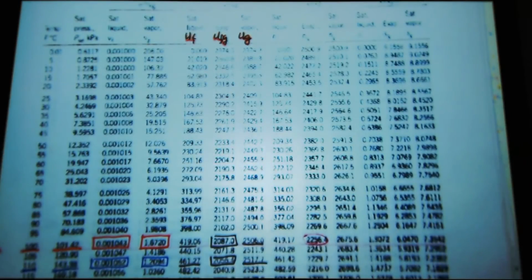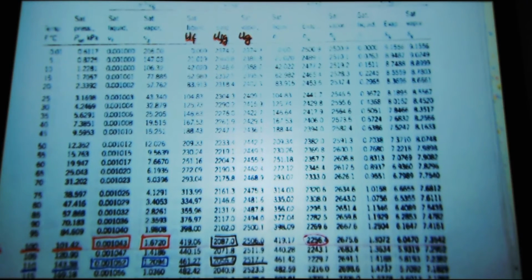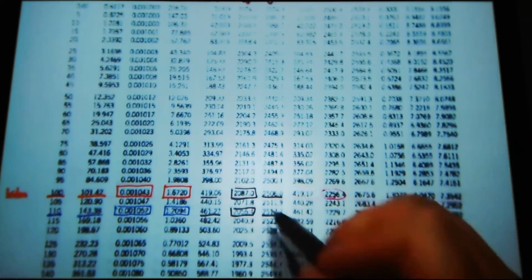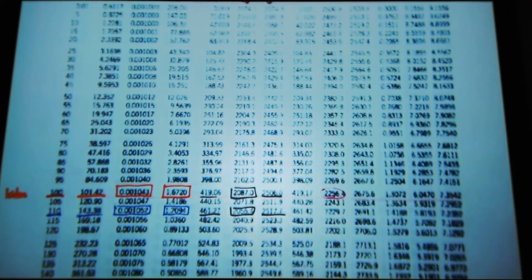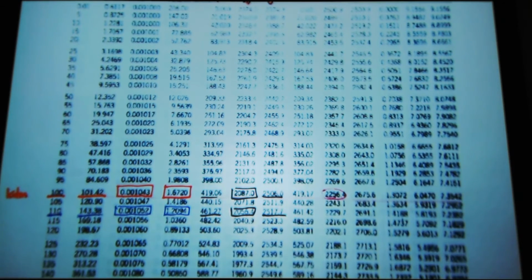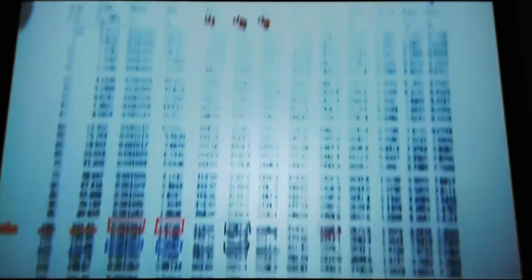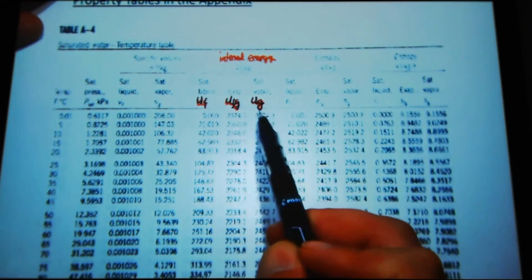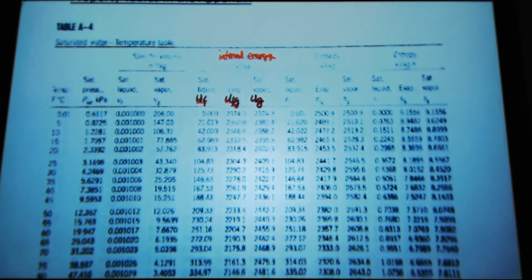And then I could go all the way up to the critical point, and at the critical point, this number would approach 0. So as it went to higher and higher temperature, at some point the width of my bell curve would approach 0, and I wouldn't be able to distinguish whether it's internal energy of fluid or internal energy of gas, because my fluid has a split personality.